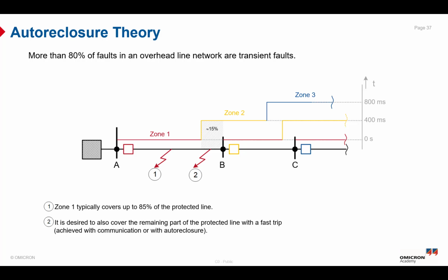They are not sustained faults, and they are commonly caused by lightning surges, switching surges, swinging wires, and temporary contact with objects, and so on. After a short time de-energization, the arc extinguishes and the line could be reconnected or reclosed successfully.